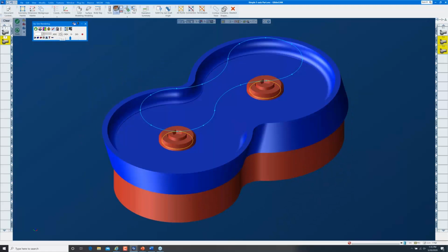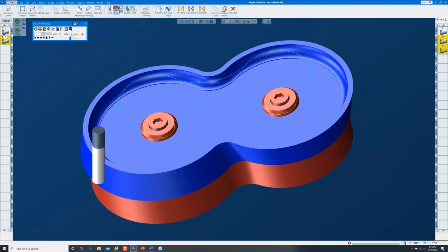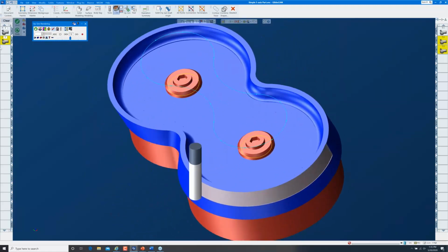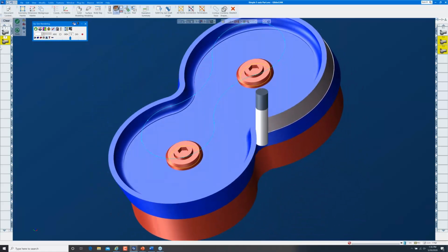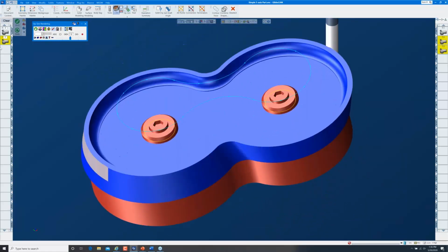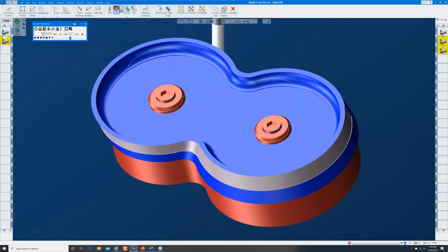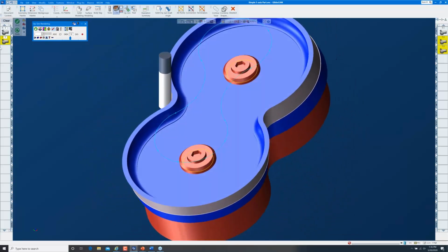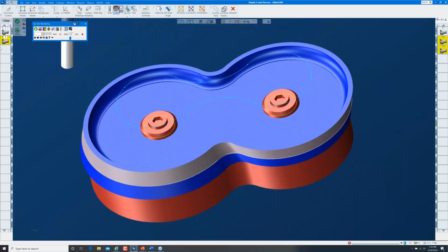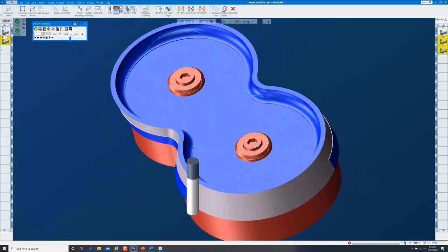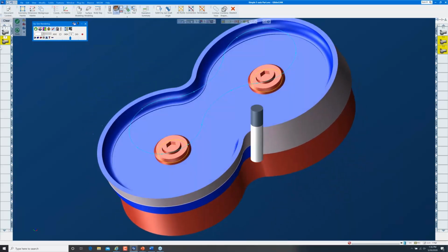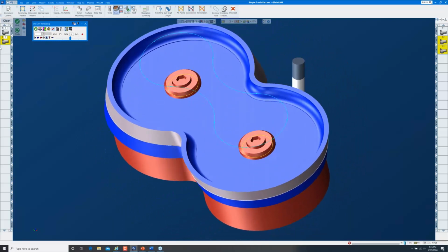All right, in the, I don't know, the last half hour, 35 minutes or so, we haven't gotten in a rush. We've taken our time, and yet we programmed a 5-axis finishing pass on the undercut radius. We tweaked that toolpath. We tweaked it again to provide gouge avoidance and developed roughing and finishing toolpath for a score profile.